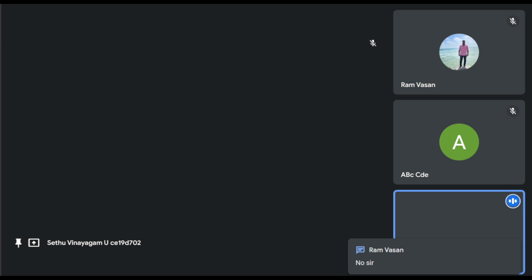It is 60 kmph, and in the formula we use V in kmph, and 2A, where A is 2.5 meter per second square deceleration rate, so 2 into 2.5 plus 19.6 into gradient, which is 3%, but we have to use it in decimal format, so it's 0.03. Substitute that, and this will come out to be approximately 4 seconds, right? So the right answer is 4 seconds for the yellow change interval.